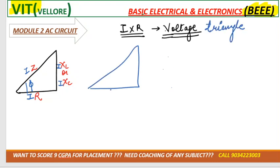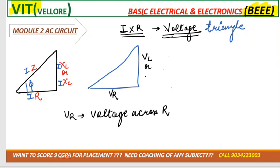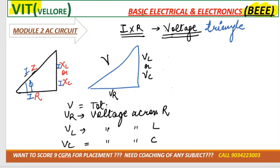In the voltage triangle, on the base we can take VR, right? VR is the voltage across the resistor. On the perpendicular we can take VL or VC. VL is the voltage across L, VC is the voltage across C, right? Here V is the total voltage, because total current and impedance is the total combination, right? V is the total voltage.